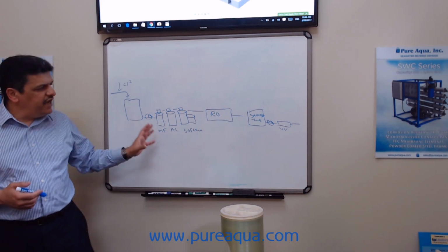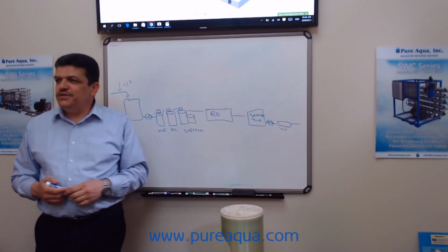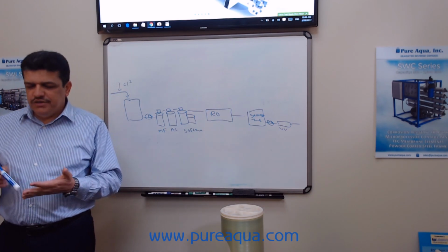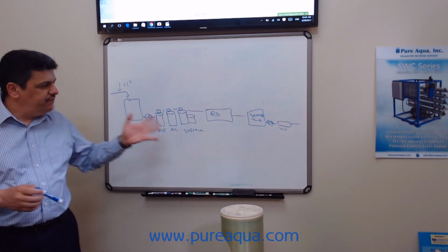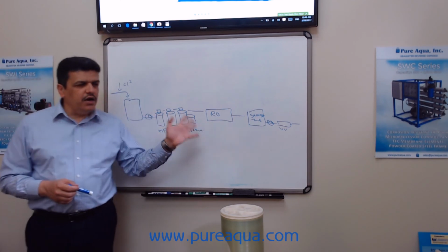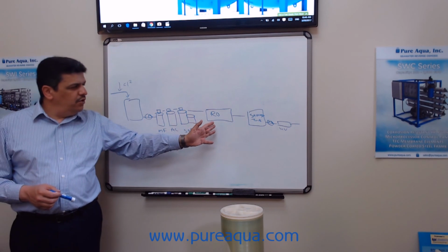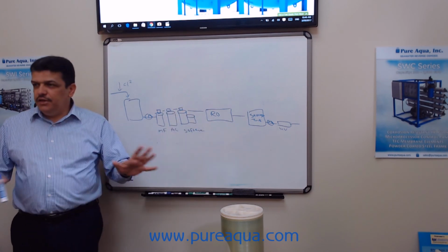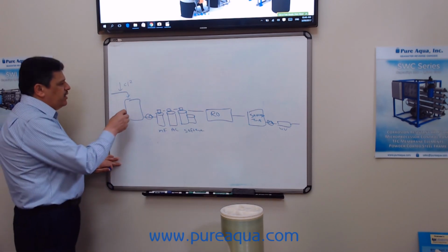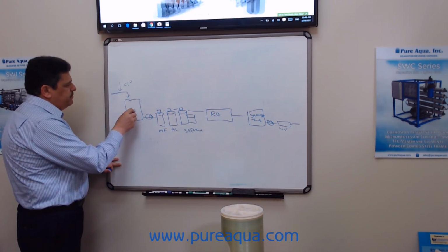Now, the big challenge is the reverse osmosis is going to reduce the TDS, that's what we want. TDS, viruses, bacteria, and all those things left over from the water. Now, the RO is ready to accept this water, and hopefully everything is going to be good. The design is good. If we assume that the water here is about, let's say, 2,000 ppm,